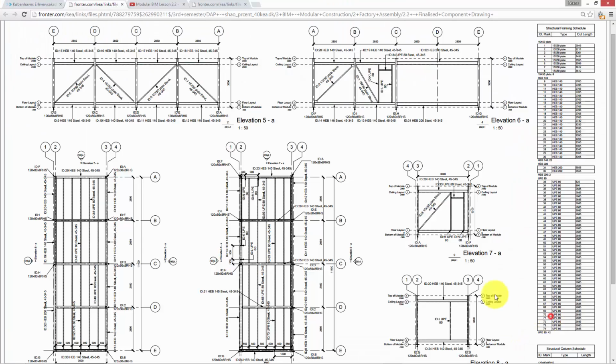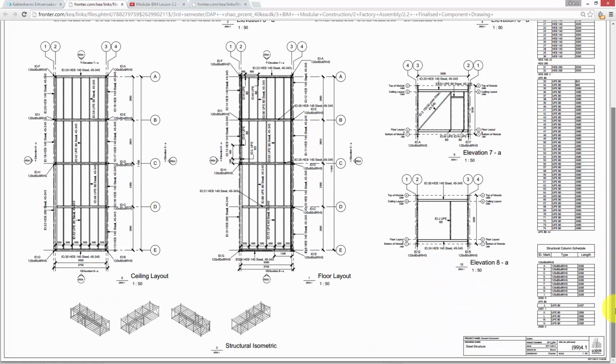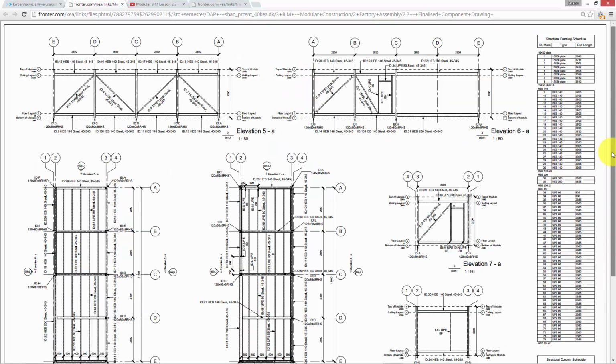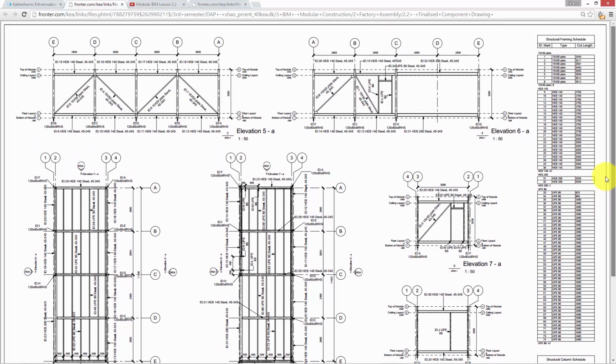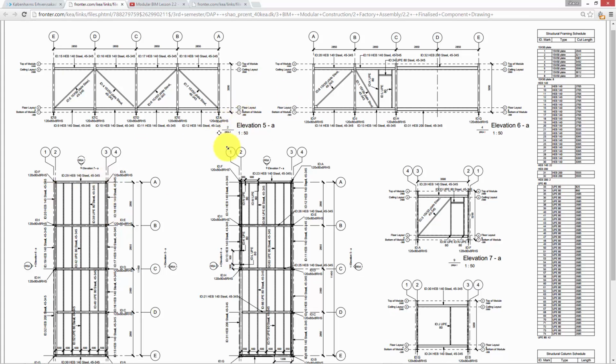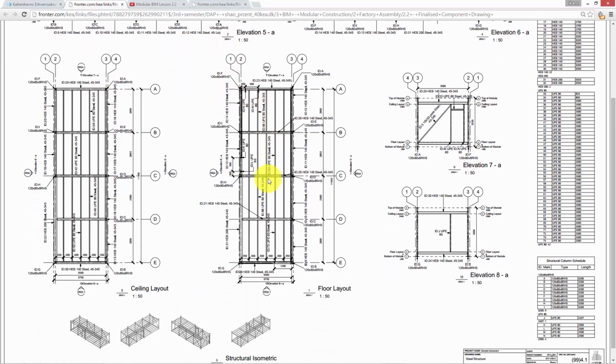Oh. Just to give you an example of the type of drawings that you produce. This is from the third semester Revit thing I did a couple of years ago. Which semester, sorry? Third semester, and this is just a component drawing that comes directly from the same system I was talking about. So these are just beam systems. This is a framing elevation, and it's just tagged. So all the structural elements in there, all this text and so forth, is automatically within the system. So you just have to use a tag structural elements, and it will print the information on the drawing for you. So this drawing took about 15 minutes to make, because the information was already in the 3D model.